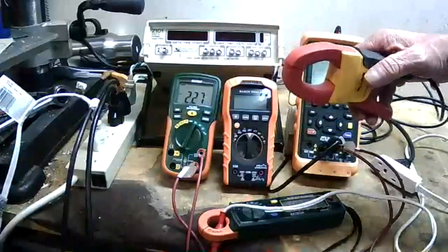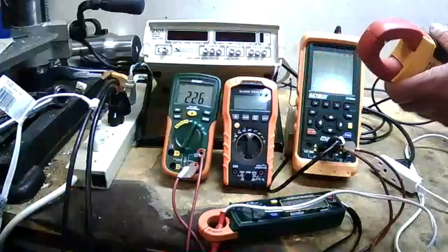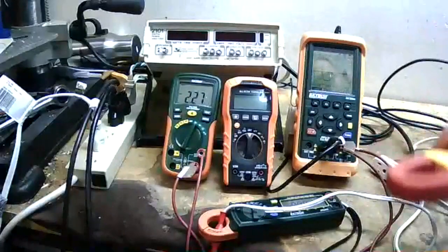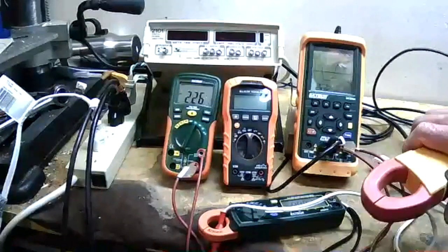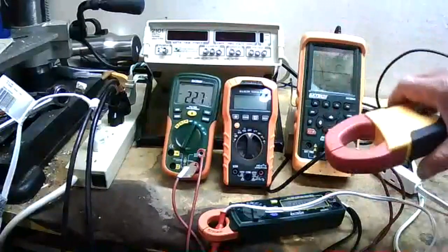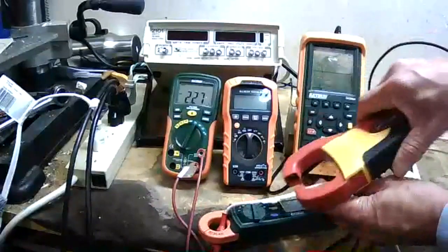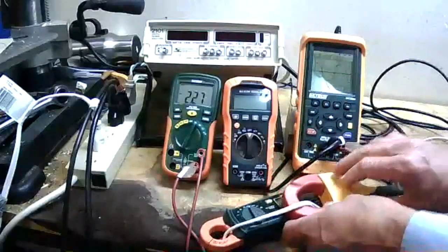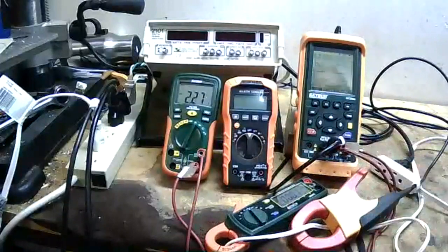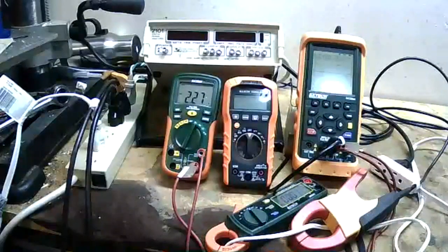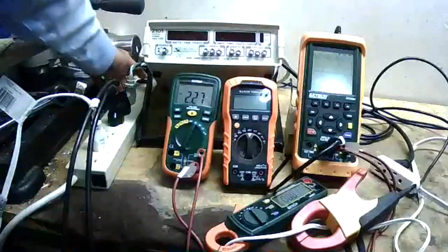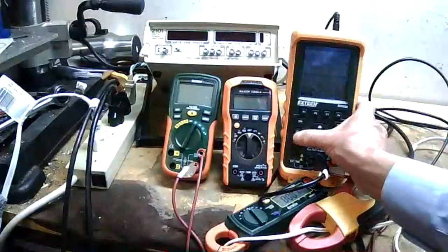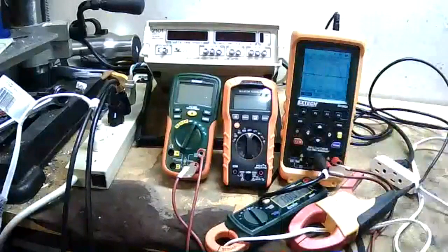This is the best way, and it's the way to measure it when you're doing work like this. So, where the clamp-on ammeter is, I will also clamp on this current clamp. And now the oscilloscope is measuring voltage on channel A, current on channel B. Turn the power to the circuit back on. Turn the light on the scope.